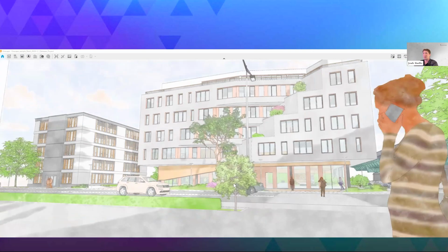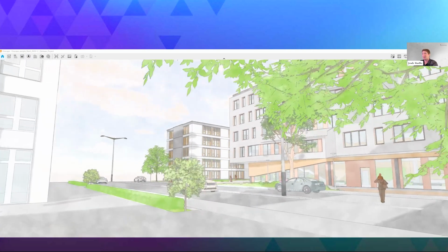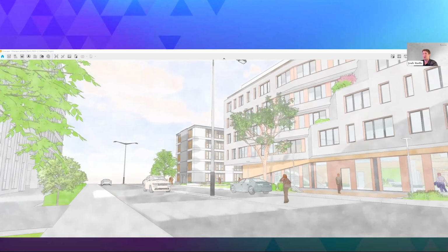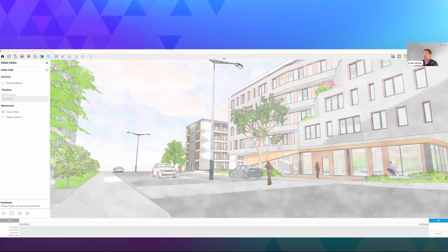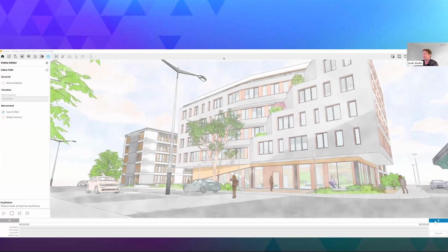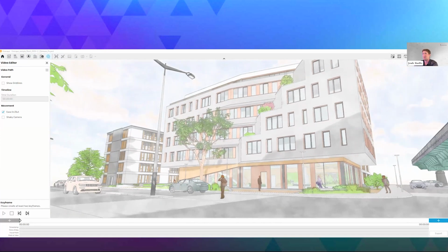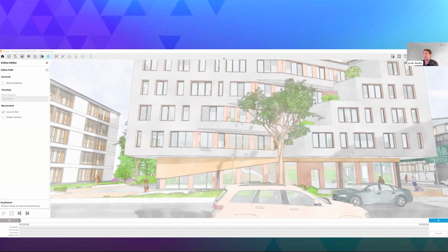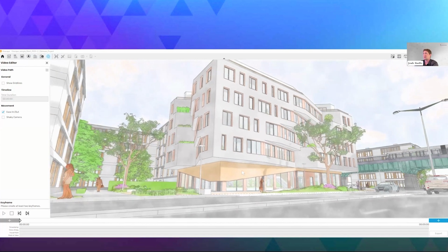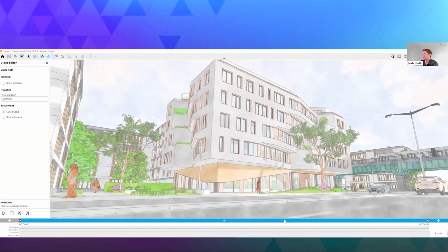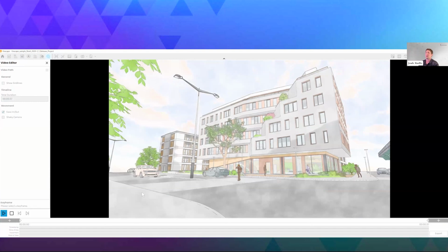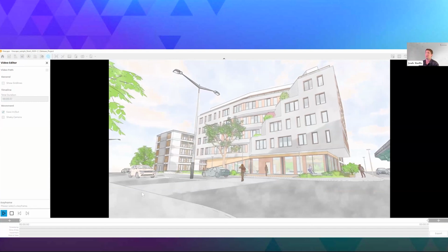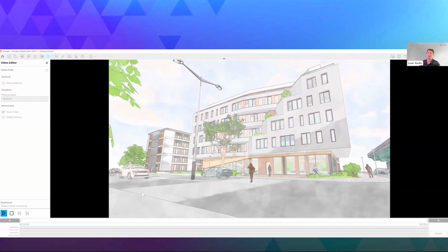And then also, again, this goes for batch rendering, still rendering, and also video walkthroughs too. So if we wanted to do a little walkthrough, we could hit the plus button to add a keyframe, and then navigate over to where we want to go next. Something like that. Add the plus button again, and then hit preview. There we go. Hit preview. And now you get a nice video preview of what this is going to look like in a watercolor effect.